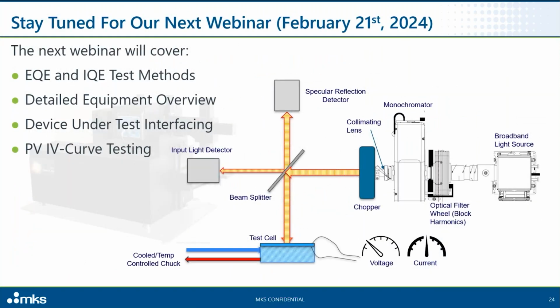And additionally, if you're trying to do IQE, this is actually an excellent slide, you'll need another meter, a method of capturing and also measuring any reflected light off of the test cell, so that you can determine how many photons were reflected from it. Hopefully that answers the question.